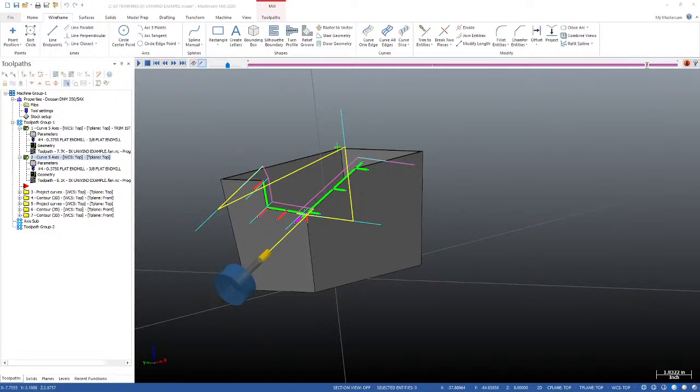We try to measure the arc second error, and basically we're at less than 1 arc second. Our measuring equipment is some of the highest laser calibrated Renishaw systems, and we have difficulty detecting the error on both the B and the C axis. So for doing 5-axis work, it's absolutely just incredible.